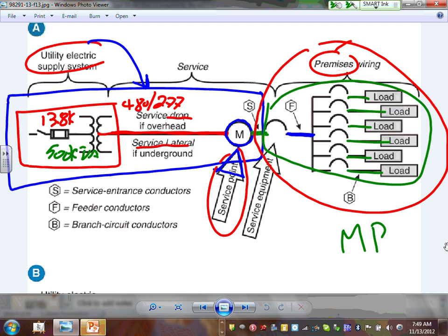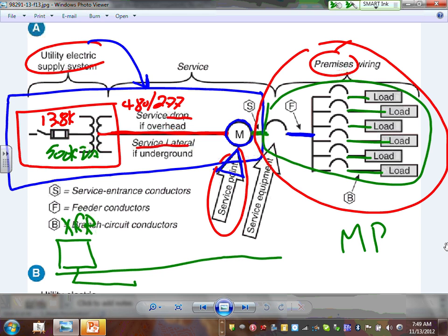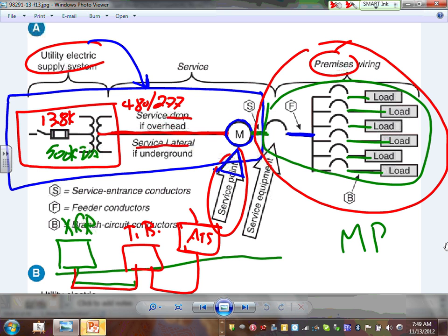Any comments, any questions, guys? Let me draw the riser that we had. If you remember, here's my transformer from Excel that we did. We came from underground, you remember that? And we went to the termination box, or CT box. Then we went to the main auto transfer switch in our building, and from the auto transfer switch into my main panel. I'm not showing the generator, I'm just showing the power.